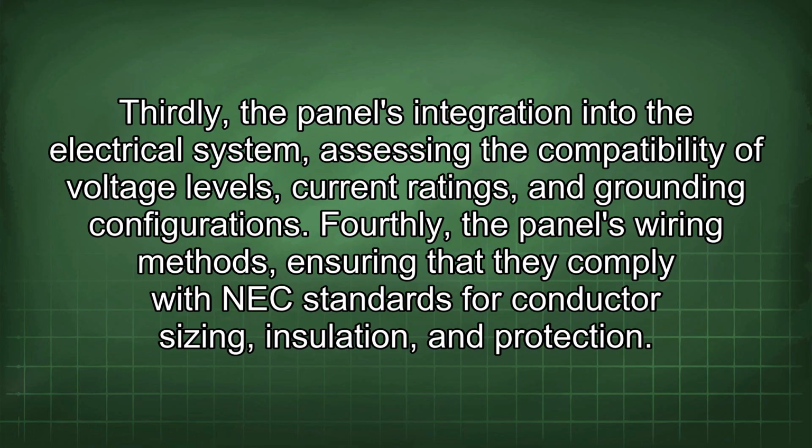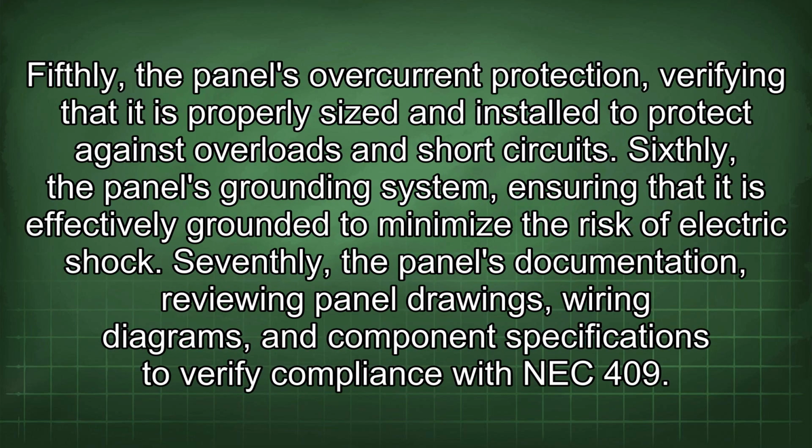Thirdly, the panel's integration into the electrical system, assessing the compatibility of voltage levels, current ratings, and grounding configurations. Fourthly, the panel's wiring methods, ensuring that they comply with NEC standards for conductor sizing, insulation, and protection. Fifthly, the panel's overcurrent protection, verifying that it is properly sized and installed to protect against overloads and short circuits.